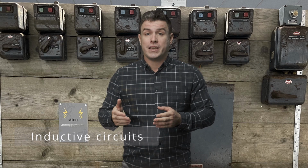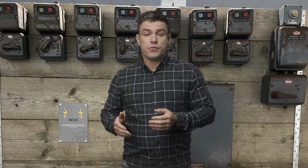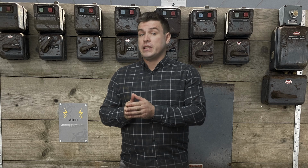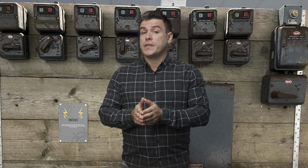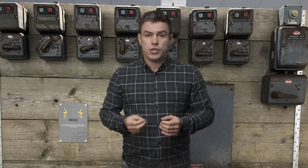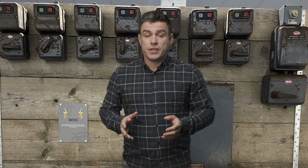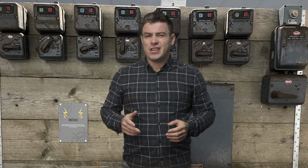An inductive circuit is similar, except the opposite way. The energy would be stored in the magnetic field of the inductor and then fed back to the circuit each cycle. In both of these types of circuit, the energy is effectively stored and not used, but for such a short amount of time. Most circuits are likely to have a mix of resistive, capacitive and inductive loads. This was all pretty new to me and takes a bit of time to suss out and get your head around it.